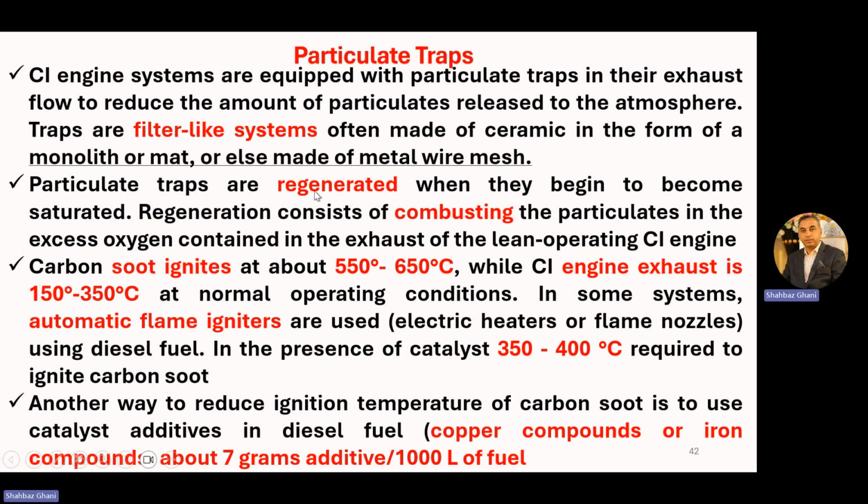Particulate traps are regenerated when they begin to become saturated. Regeneration consists of combusting the particulates in the excess oxygen contained in the exhaust of the lean operating CI engine. So we have an excess amount of oxygen, and due to that, the particulates are combusted.